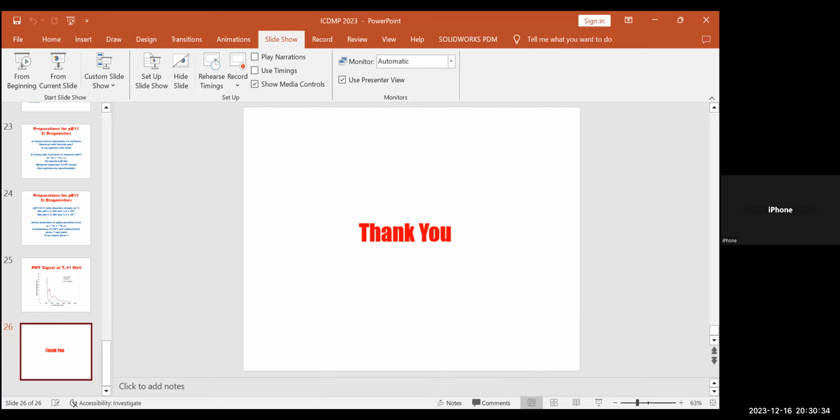The problem is you can degas those very easily after a temperature of 200 degrees or under high vacuum and also ion bombardment. You can start to degas them again.